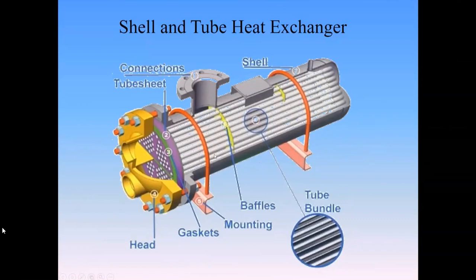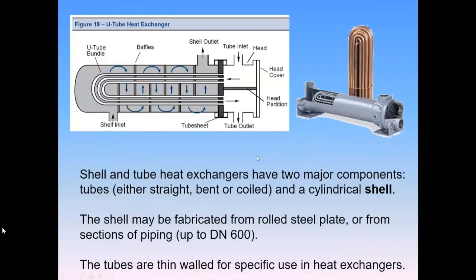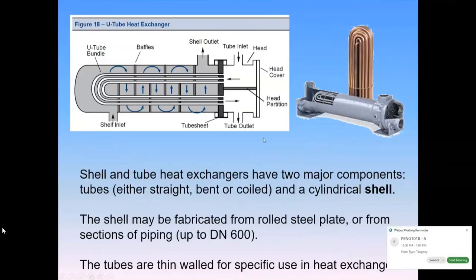And realistically, these things look and perform similarly to a water tube boiler. Yeah, exactly. So it looks kind of like a boiler, right? We've got different designs of boilers, and these boilers are just heat exchangers where we have a phase change that happens. So these share a lot of the design ideas with boilers and other components. Okay, so what we have would be a U-tube heat exchanger.